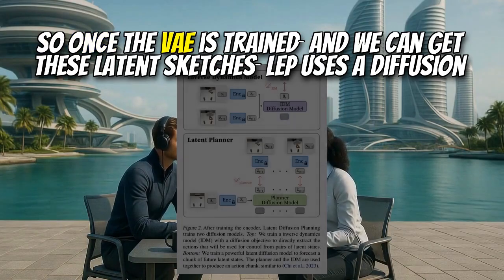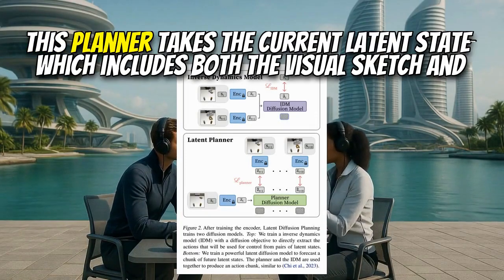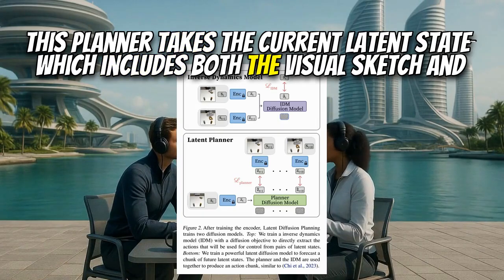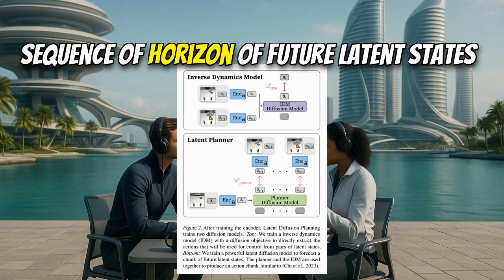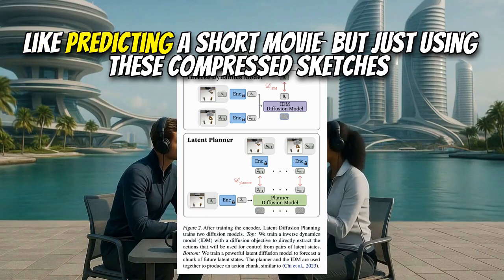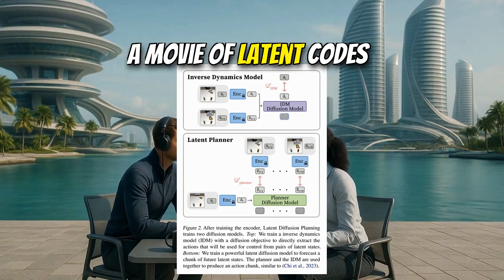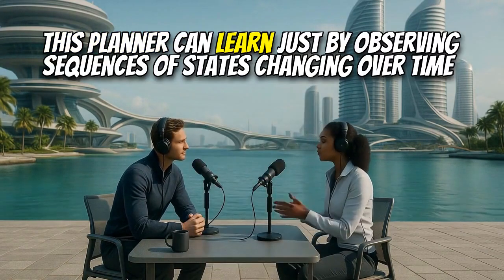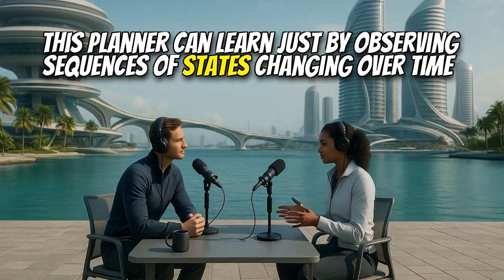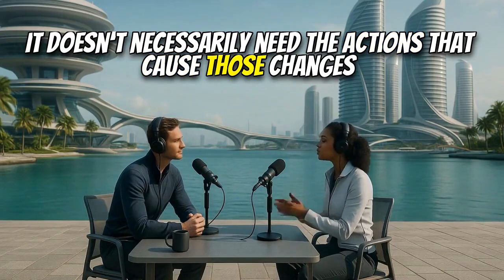Right, so once the VAE is trained and we can get these latent sketches, LDP uses a diffusion model as the planner. This planner takes the current latent state, which includes both the visual sketch and maybe the robot's own joint positions, its proprioception, and it forecasts a whole sequence or horizon of future latent states. Like predicting a short movie, but just using these compressed sketches. Yeah, exactly. A movie of latent codes. And here's a key thing. This planner can learn just by observing sequences of states changing over time. It doesn't necessarily need the actions that cause those changes.